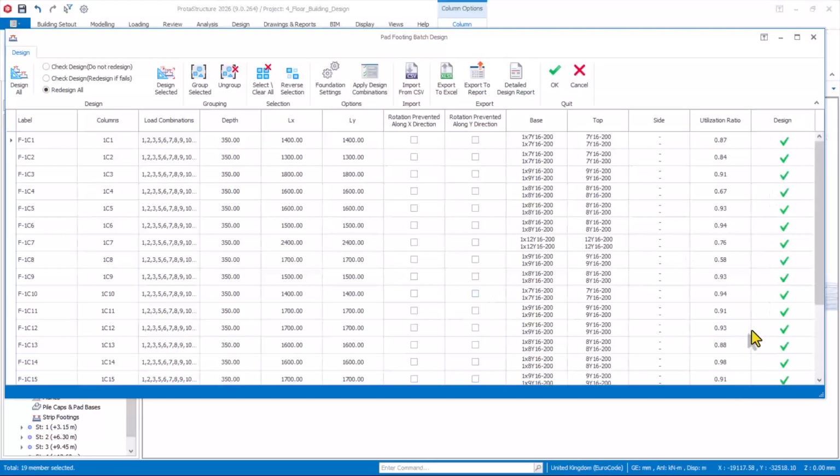Alright, the footings have been designed, and you can see the spacing for the reinforcement is being maintained successfully. Again, you can see we have 1.4 by 1.4. The square footing LSLY is also being maintained successfully. We have a very large footing right here, which is 2.4. This is quite large. We need to know where we have that large footing. It should be at the staircase provisions.